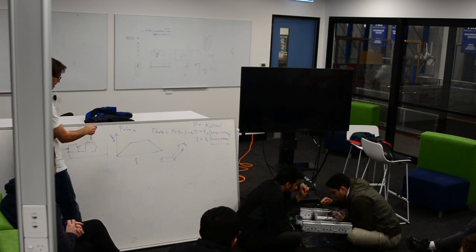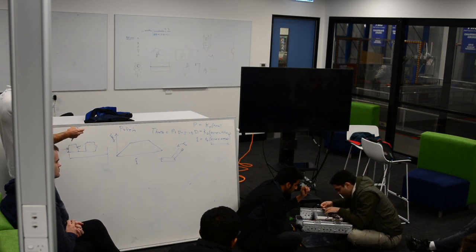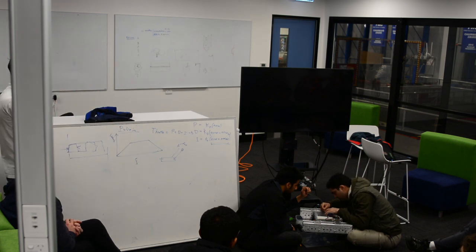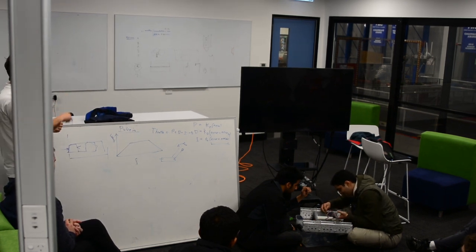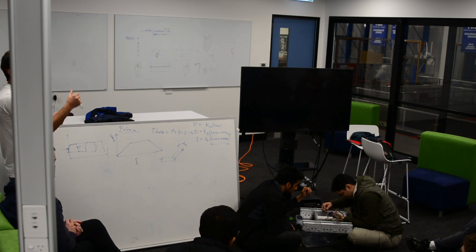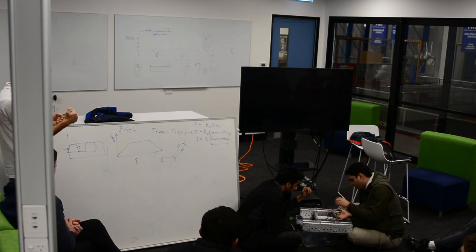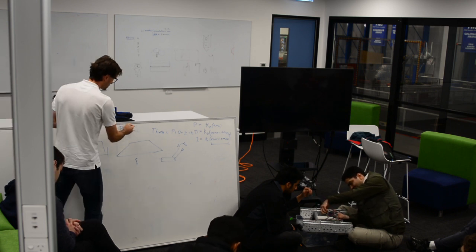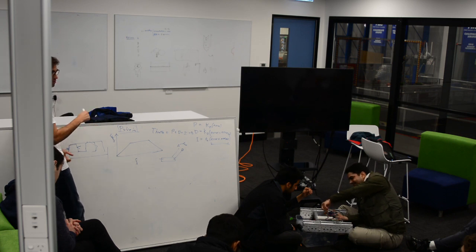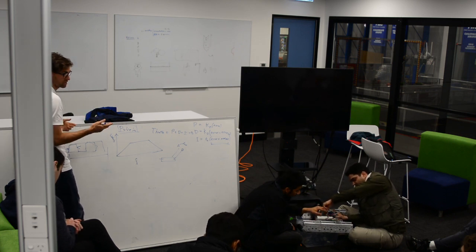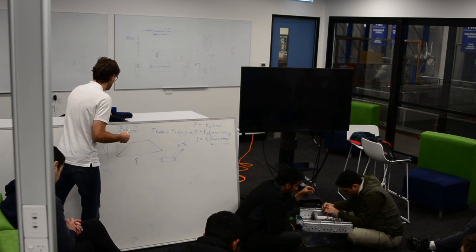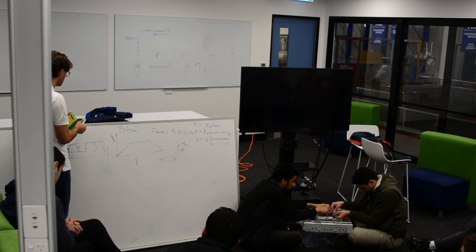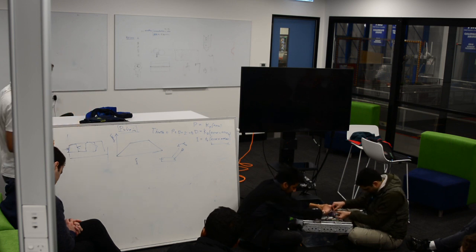The only issue is if you're going slow, and this pulse takes a long time, your code hangs waiting for that pulse to go low. So the pulse goes high, it starts a timer, the pulse stays high, it keeps the timer running till the pulse goes low, and your code can move on. So there is a time cost to using pulseIn. It has a timeout feature that you might limit at 1/10 of a second or 100th of a second, and then your speed measurement isn't going to make any sense below a certain rate, right?